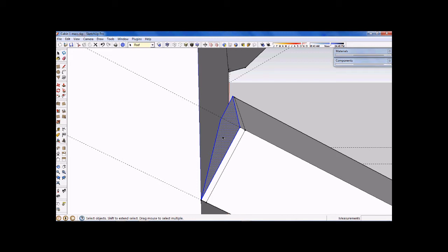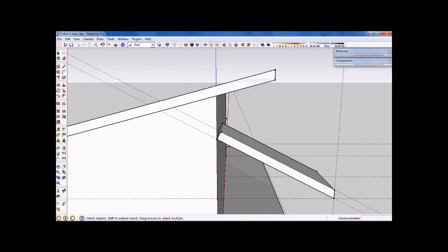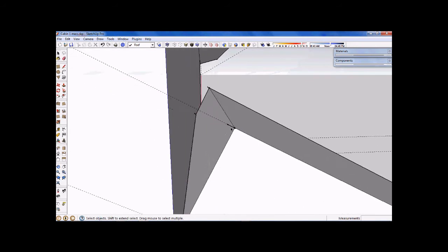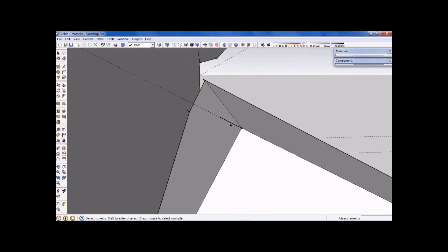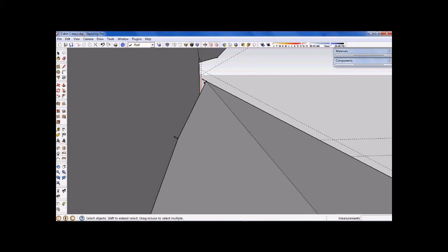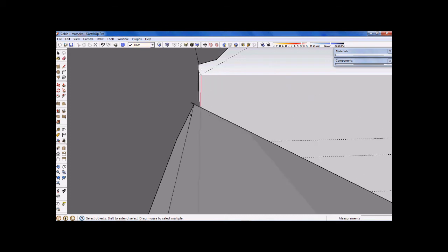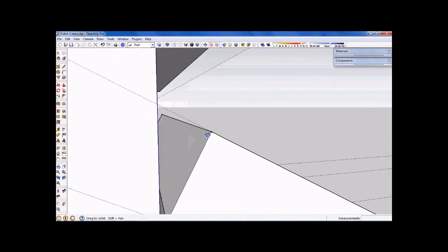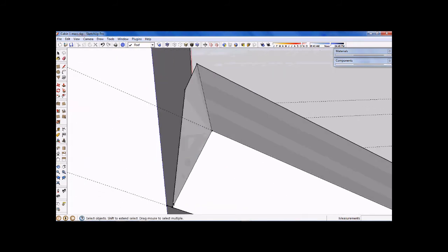These little lines here, you'll want to delete those one at a time, and you've now got a bit of a roof face that's a little bit away from the main wall. Okay, a little bit more tidying up, and I've got that one, this one down here. Okay, so that's nicely tidied and leaving our main wall intact.